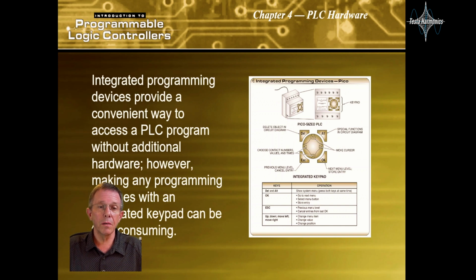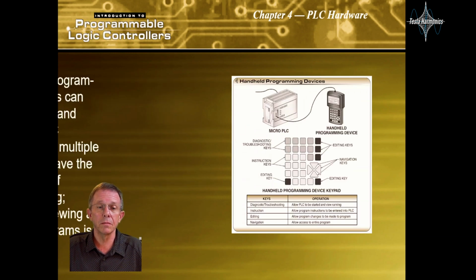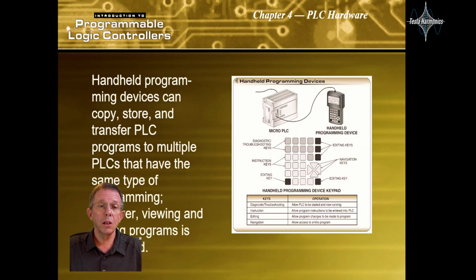Integrated programming devices provide a convenient way to access a PLC program without additional hardware. However, making any program changes with an integrated keypad can be time-consuming. Handheld programming devices can copy, store, and transfer PLC programs to multiple PLCs that have the same type of programming. However, viewing and editing programs is still limited.